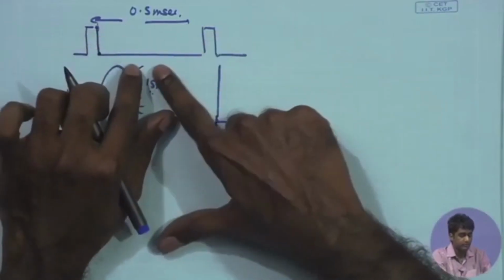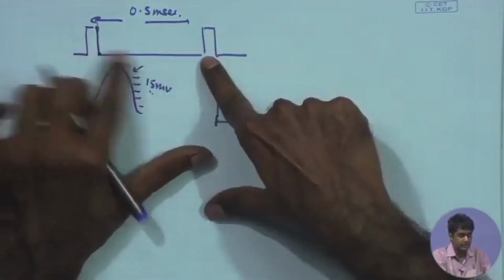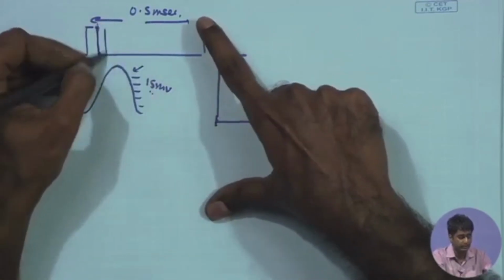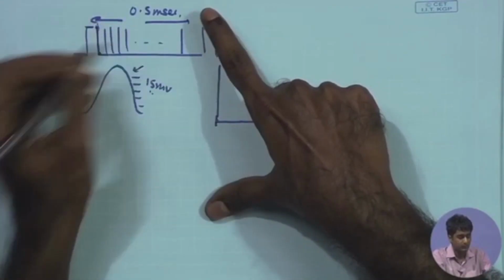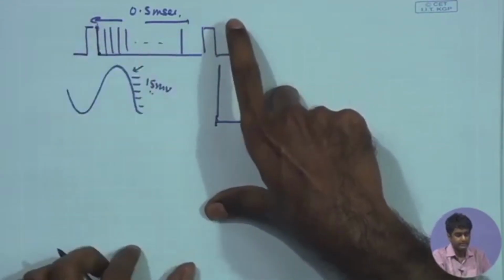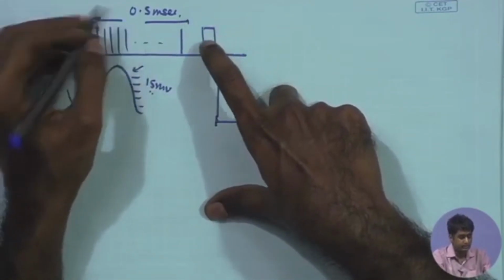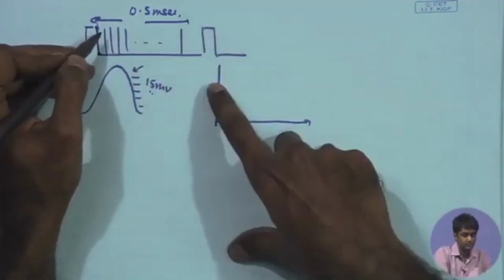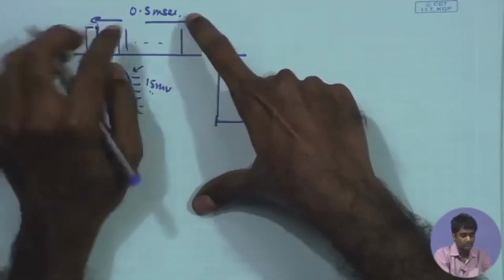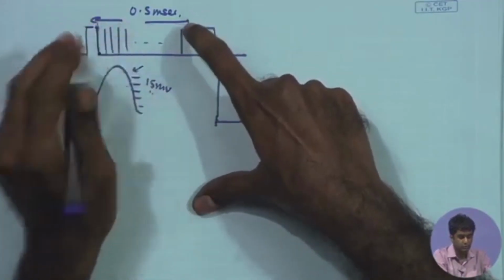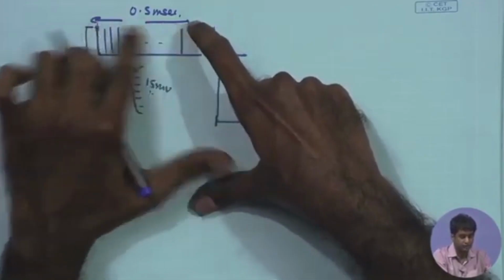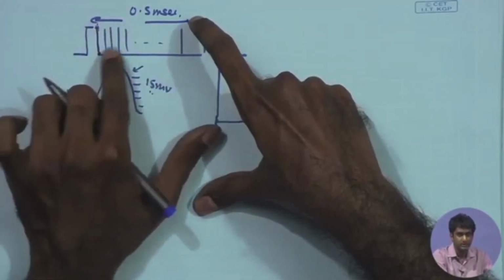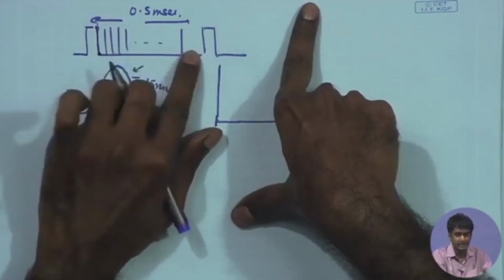Therefore, of course, if you have to measure the entire signal in terms of time duration in this entire 0.5 millisecond, I would like to divide this into correspondingly 127 segments. And as a result, if I look at the counter, which is supposed to give me the count, or the magnitude of this duration, and hence the magnitude of the input signal, that is supposed to be driven by a certain clock frequency corresponding to this time division.